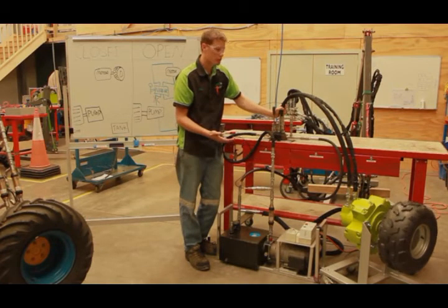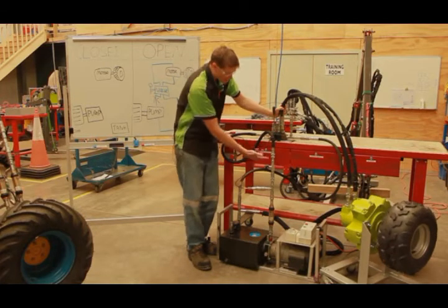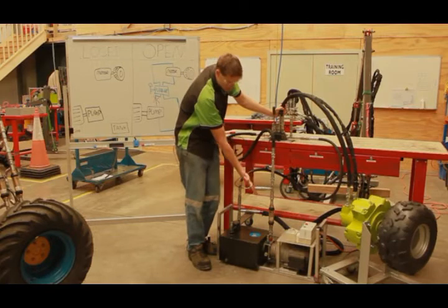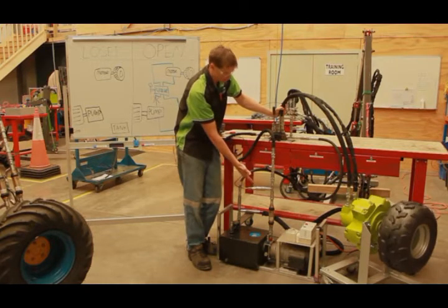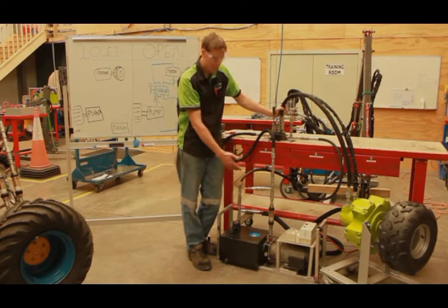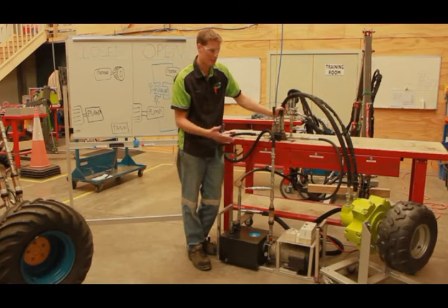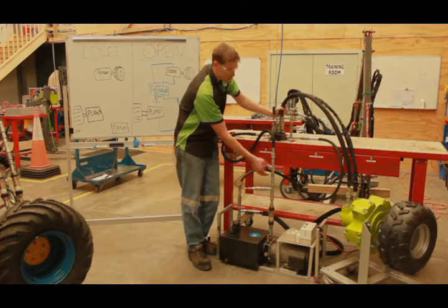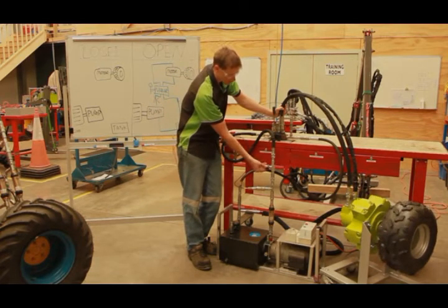The reason for this is that any oil that doesn't come through here has to go somewhere else. And in this particular system, an open loop system, it'll generally go over a relief valve, or it may be a compensated system, but we'll talk about that at another time. But in this case, to speed up the motor again, I need to open the flow control, and I take away all that restriction in my system.